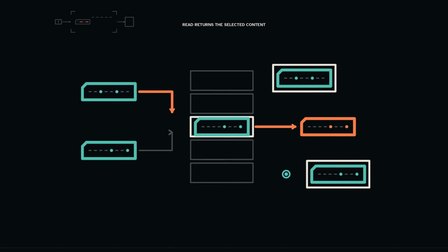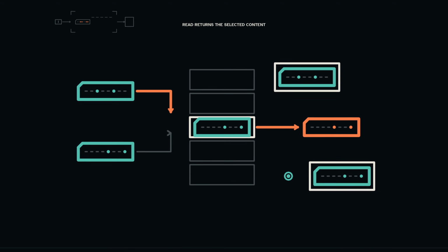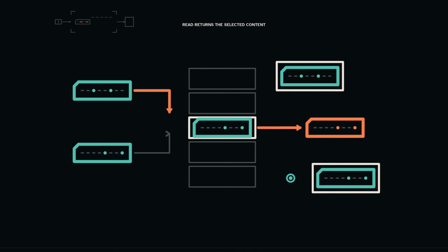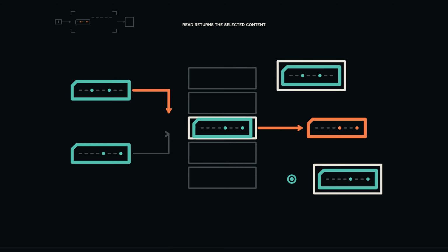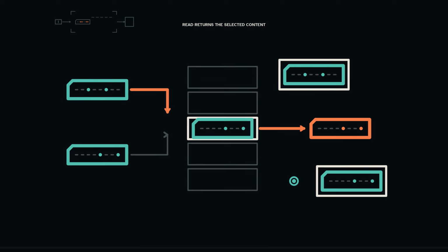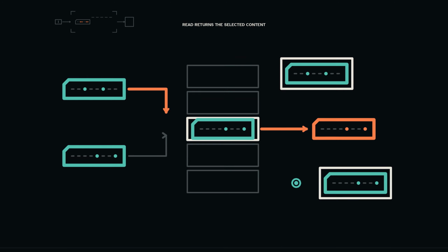Trace a new case. Address hexadecimal 24 contains hexadecimal C7. R1 holds hexadecimal 09. A write to address 24 is requested with R1 as source, and state the three committed changes in order. MAR captures 24, MDR captures 09. Memory 24 captures 09 on the write edge.